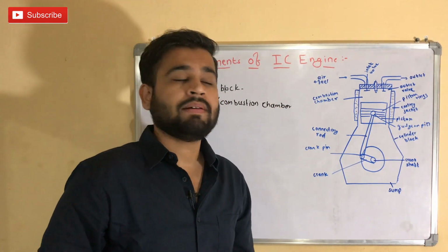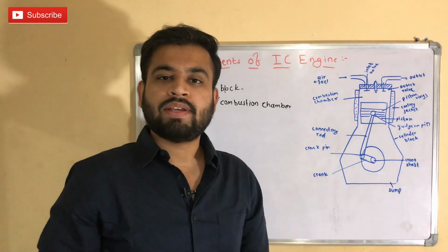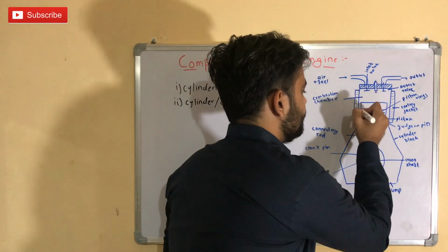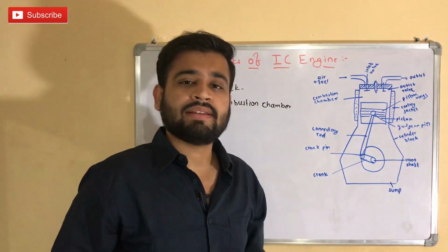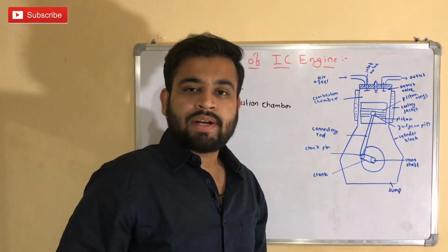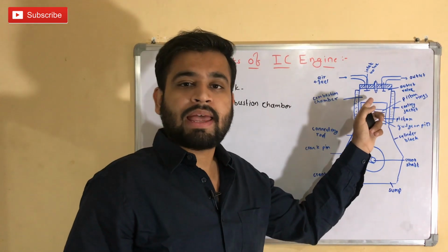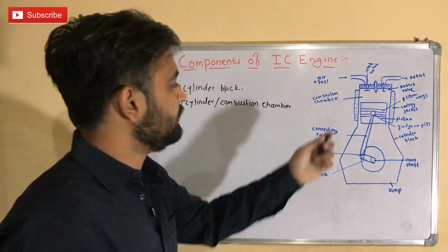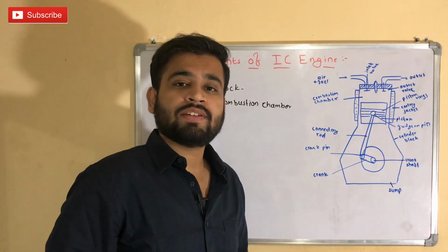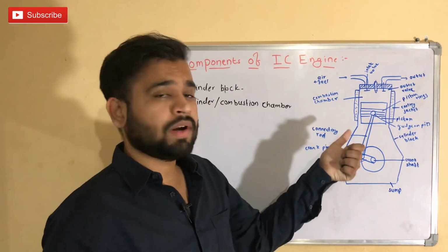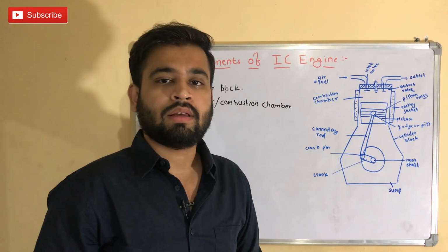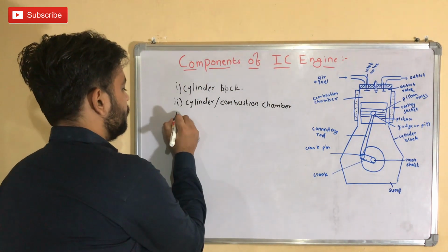The cylinder is nothing but a cylindrical vessel in which all the thermodynamic processes happen. In this case, this is a cylinder in which the piston is reciprocating. In the cylinder, the air-fuel mixture is admitted and compressed, and power is produced by the combustion process. The inside lining of this cylinder is finished with high precision to avoid friction between the cylinder walls and the piston during the cycle. Our next component is the piston.